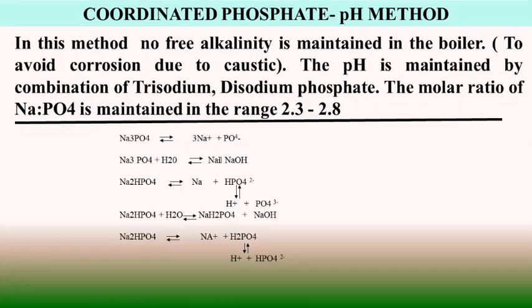In high pressure and high heat transfer rate boilers, the internal treatment must be so strong that there are almost no solids within the treated water. The potential of caustic attack on boiler metal may increase with increasing pressure, as free caustic alkalinity may result if it is not minimized. So for that reason the coordinated phosphate program is preferred.